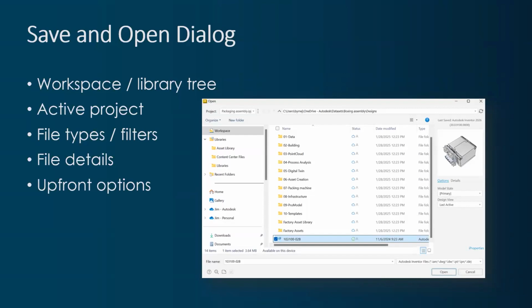And if you select an assembly, there's an option that I really like, and I'm sure those of you that have been using Inventor for a number of years would also find this valuable. There's an option to skip unresolved links. So if you've lost a file or you don't have a complete assembly, you can simply skip the unresolved items on the far right side. You won't see it in the view I've got on screen at the moment, but certainly in the assembly type situation, you would have that option. So there's quite a few options there for deferring updates in flat patterns. All of this is now displayed directly on the file open dialog. So it's nice Autodesk have made some updates to that.